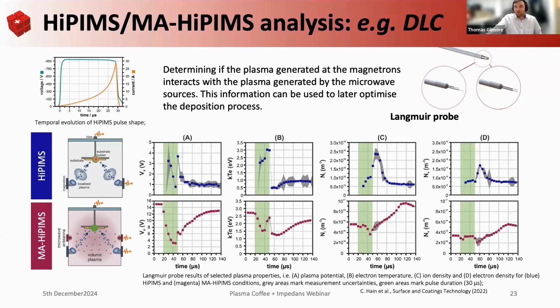Another question: in the case of sputter systems where the substrate cannot be biased, is it possible to achieve similar effects by using a positive pulse after the primary negative HiPIMS pulse? Yes, so that's the bipolar HiPIMS. I've not done so much bipolar sputtering, but from what I've read, it is possible to use this positive kick instead of a bias.